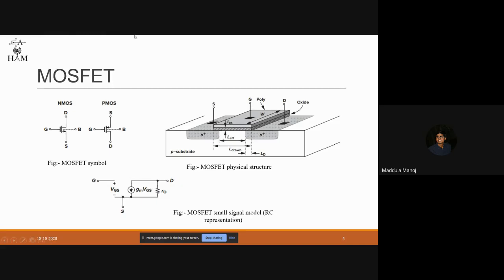And we have a gate which is isolated from source and drain. On the gate there is a metal which makes contact with the gate, and following that there is a silicon oxide SiO2 layer, which acts as a dielectric, or simply a capacitor, which prevents any current from the gate from entering the substrate, right? When we apply a voltage at the gate, if it is less than the value which can break the barrier offered by the oxide layer, then the transistor is off.